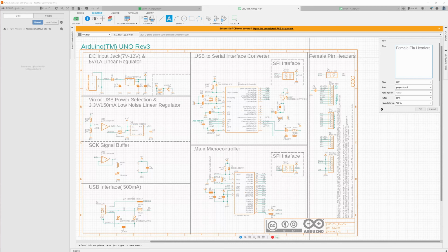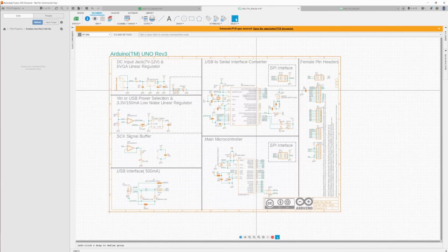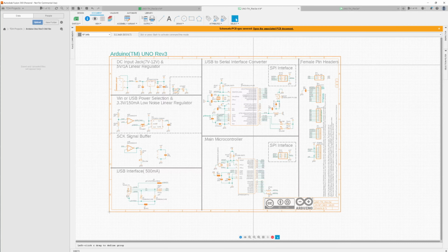And last, on the right side are the pin headers, which we use to connect sensors or signal controlling to the main microcontroller GPIOs. It's always nice to write in the schematic and specify whether this is a male connector or a female connector when you use a standard pitch connector. This is all you need to know about the Arduino Uno hardware. So I will again jump to the not edited version and the edited version.